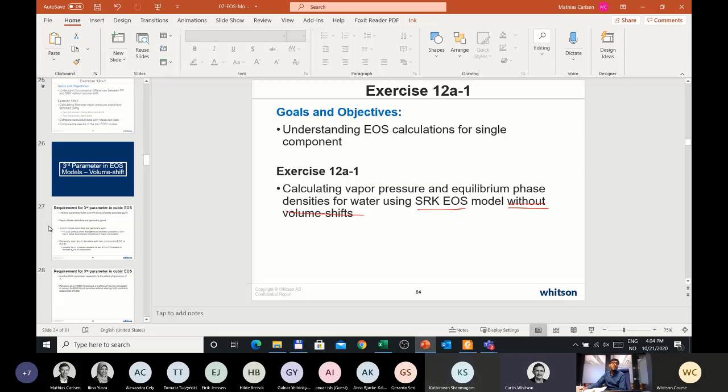I think there have been a number of publications, and one of which we did back in the late 80s, showing that the cubic equation of state can be used very accurately to get component partitioning for aqueous and non-aqueous phases in petroleum applications. You have to use a different mixing rule, but the cubic equation can be used to get quite accurate mutual solubilities.